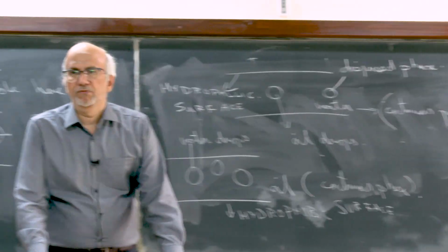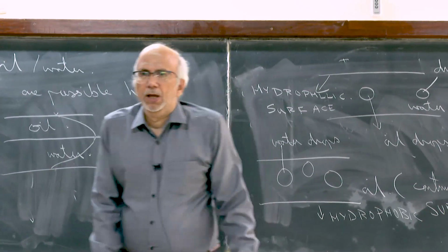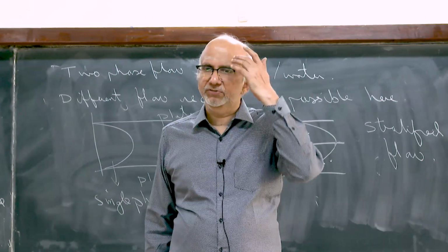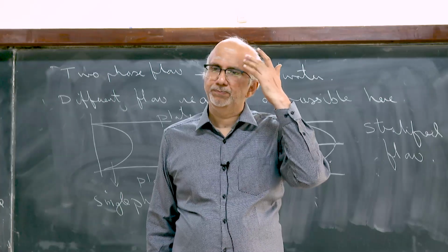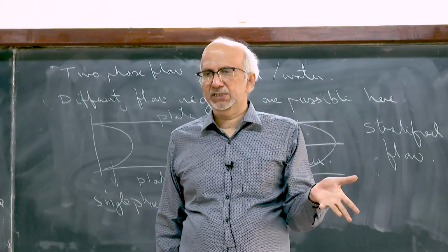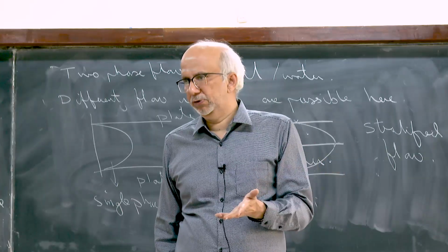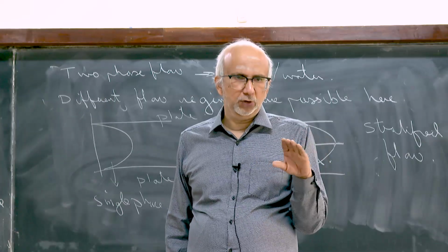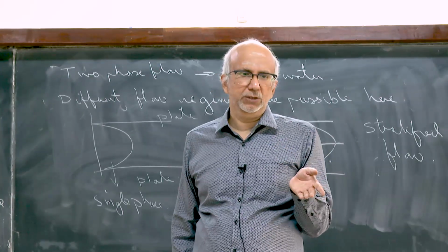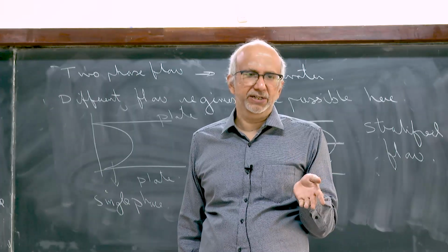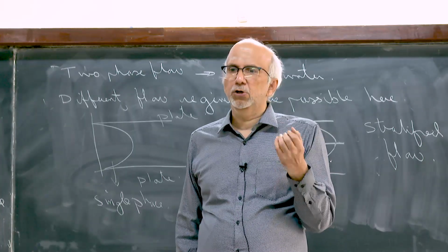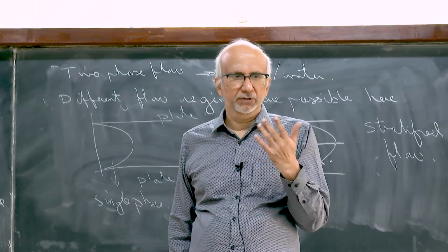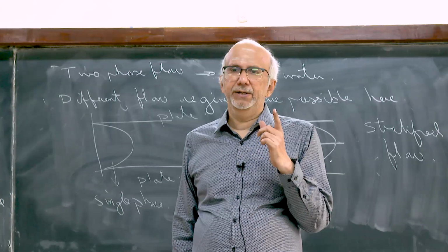The other thing which is important is the surface tension. When you talked about single phase flows, you were only interested in viscous effects, viscous forces and inertial forces. But when you have two phases, there is an interface, and there is going to be a surface tension, an interfacial tension, associated with it. So now there is one more force which comes in, the interfacial forces.